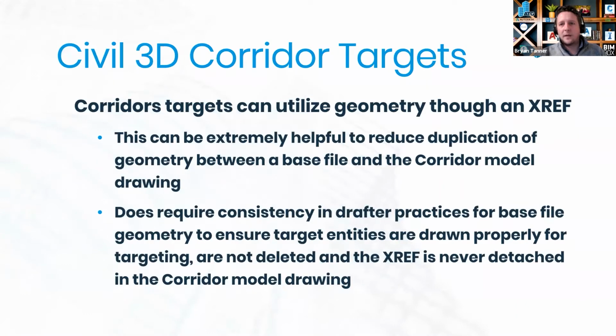If it's a project where I'm doing the baseline work while also working on the corridor, I'm going to inherently know where I need to break my line work into different segments so that I can target the geometry differently between my regions. It's also going to make me more distinctly aware of how important that baseline work in the X reference is.